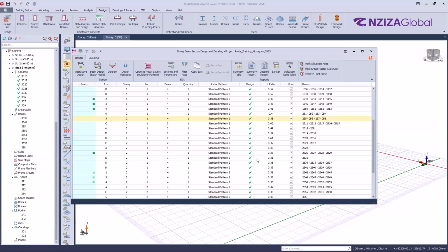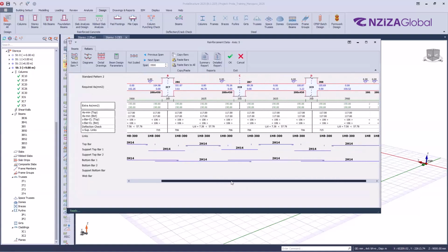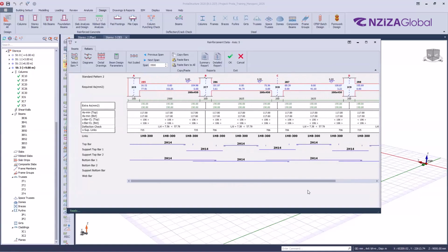So the last thing I want to show on the beam here is the rebar pattern. Okay. So if I open again the beam that we had, and I go to select rebars, there is a drop-down menu. If you click on it, we see we have different patterns. So the patterns are different ways reinforcement are arranged in a beam, layers and even the curtailing.